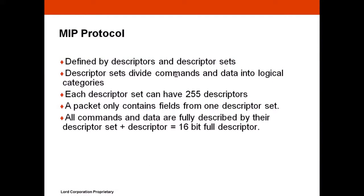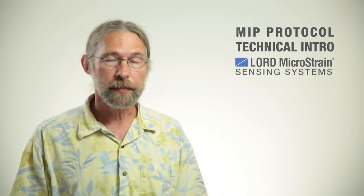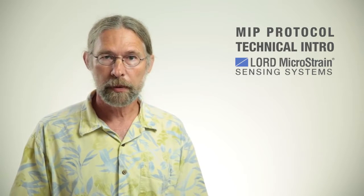The MIP protocol is what the packet supports, and the protocol depends on the descriptors and the descriptor sets. Descriptor sets divide commands and data into logical categories. I'll show you an example very shortly. Each descriptor set can have 255 descriptors, giving you a lot of room to describe different types of data and commands for a given descriptor set. A packet only contains fields from one descriptor set. That means when you get one packet, you can examine that 3rd byte in the header and find out what type of data is in that packet, and you can route it efficiently to the code in your microprocessor or your embedded system.